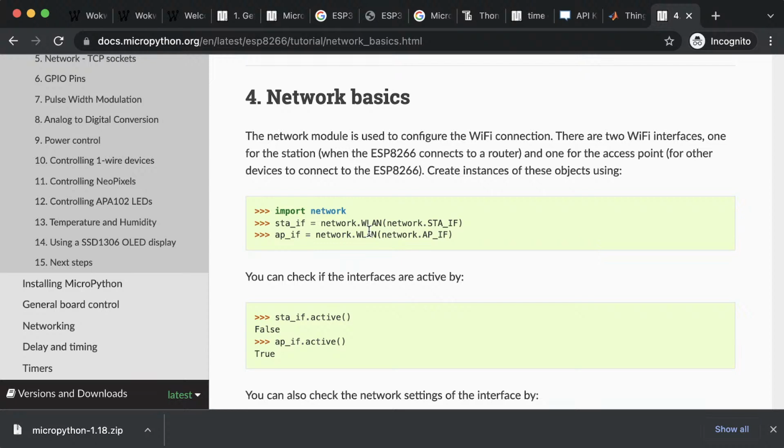Similarly, our ESP32 can act as Wi-Fi station and Wi-Fi access point. And one more thing that mobile phones can do, when in hotspot mode, is they not only give access to the data on the mobile phone, but also to the external internet. That is how it is being done, because it's acting in dual mode.